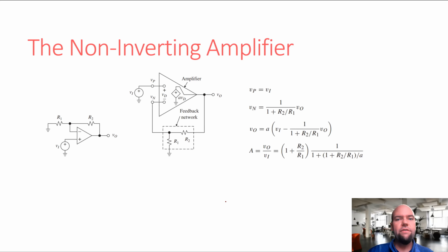But we're going to go over the non-inverting amplifier, and we're going to find the behavior of this, assuming non-ideal effects. But now we're not going to assume everything non-ideal. We're only going to assume that the gain is finite here. So we are going to analyze this, do the math for the non-inverting amplifier, only assuming that A is finite. And so we're still assuming the output resistance is 0. We're still assuming the input resistance is infinite. Let's jump into it.